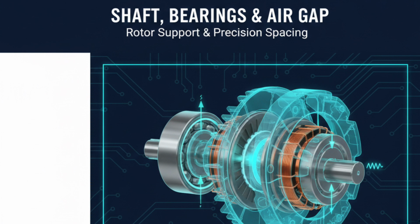Shaft, bearings and air gap. The rotor is mounted on a strong steel shaft which transmits mechanical power from the prime mover into the alternator. Bearings support this shaft and allow smooth rotation. These may be ball bearings, roller bearings, or sleeve bearings with pressurized lubrication systems in larger machines. Proper alignment and lubrication are critical on board ships because vibration and hull movement can accelerate bearing wear.